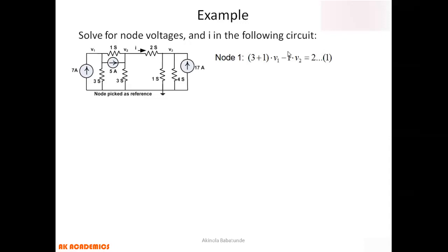So this is the minus V2 here, and this is the plus V1 here. You see 1 here, V1 minus V2 here. That's what is inside here. Also between 3S and this place, what is the voltage at this particular node? Can you see my cursor? It is 0, because it represents our ground node. The voltage at the ground node is going to be 0.